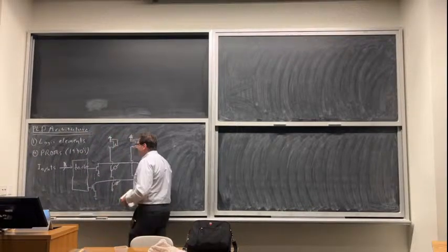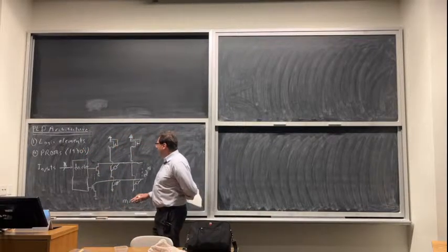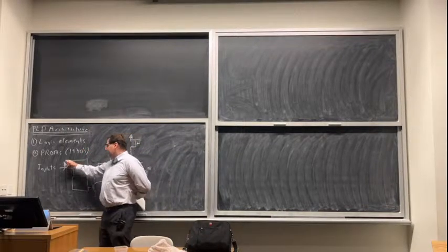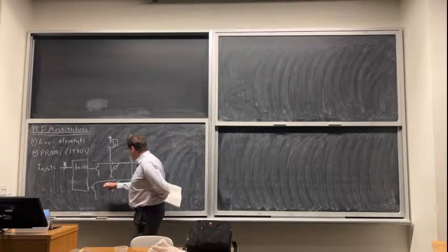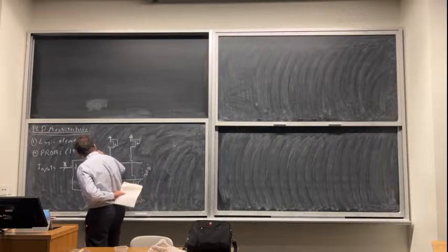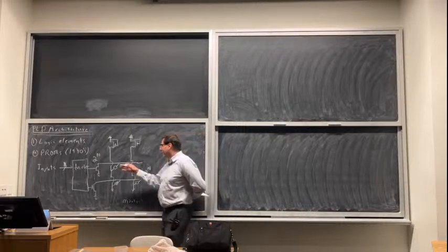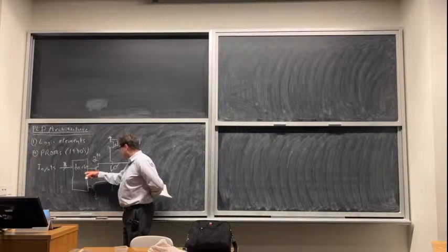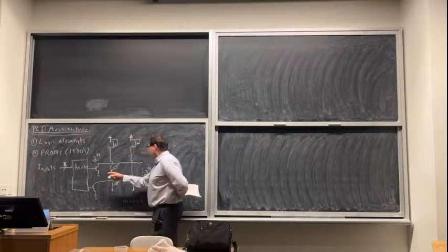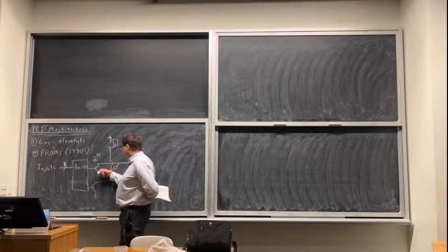So the very first programmable logic elements were programmable read-only memories. Basically you've got n inputs. Those go through a decoder. That produces basically 2 to the n of these lines. So we detect we have a different value that turns on for any bit pattern that we put in here. We put a different value on one of these lines.